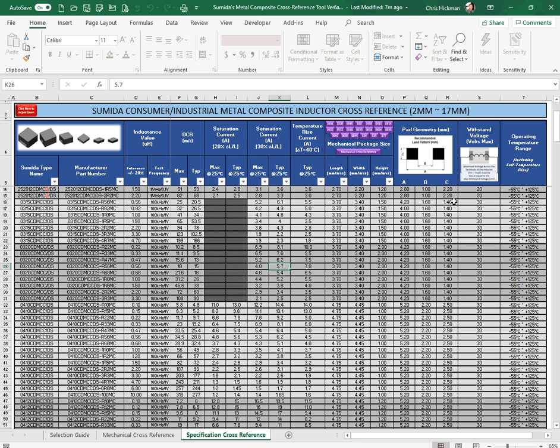Followed by withstand voltage specifications. This is the maximum voltage across the inductor. This is the maximum voltage, voltage in minus voltage out, that the inductor should see in the circuit. Above this, it is possible to degrade and, in the worst case, damage the part. And finally, normal operating temperature range. This is the full temperature range specified for these inductors. This temperature range includes the self-temp rise of the inductor. So since these parts have a 40 degree C temperature rise specification, the actual maximum ambient temperature of the surrounding environment would be about 85 C worst case at max current.